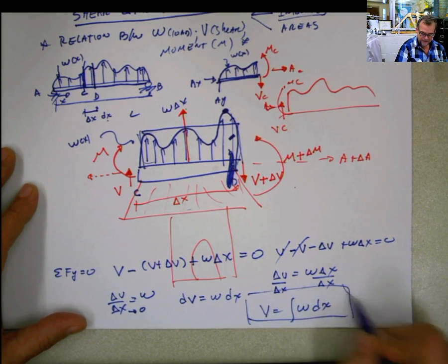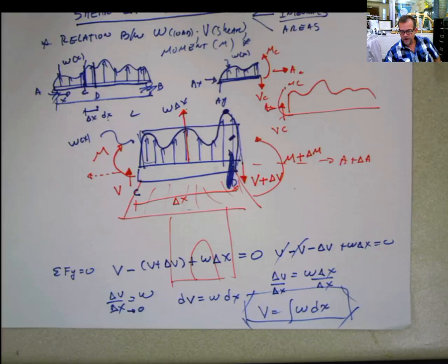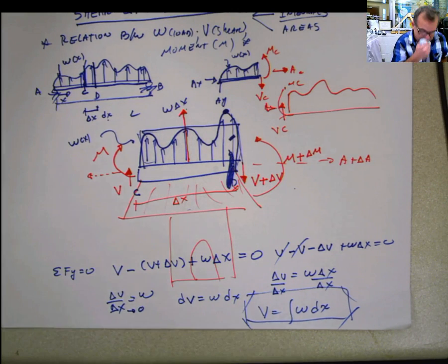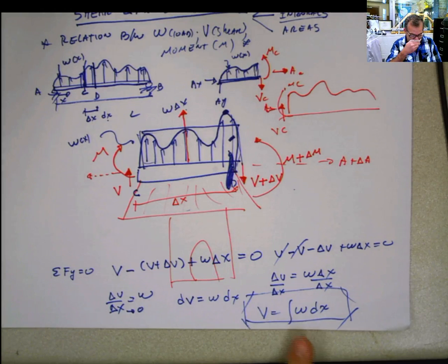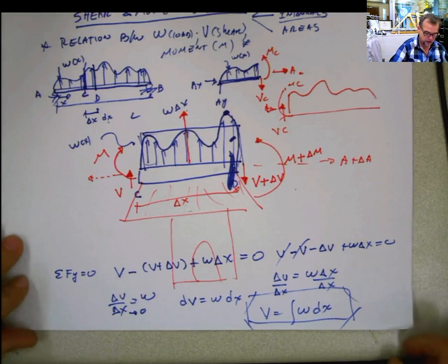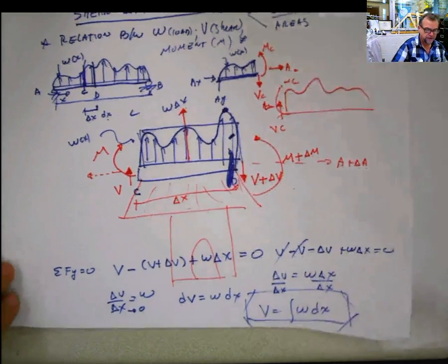And this is a very powerful equation. What that equation shows us is that every time I want to calculate the shear force at any point, I just have to calculate the integral of the function that defines the load over that distance. That's a very important equation. Now let's keep going.